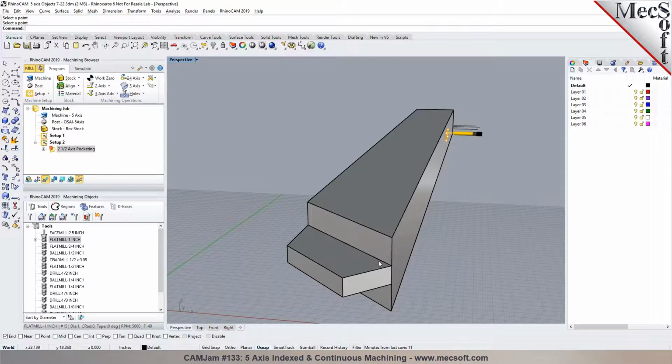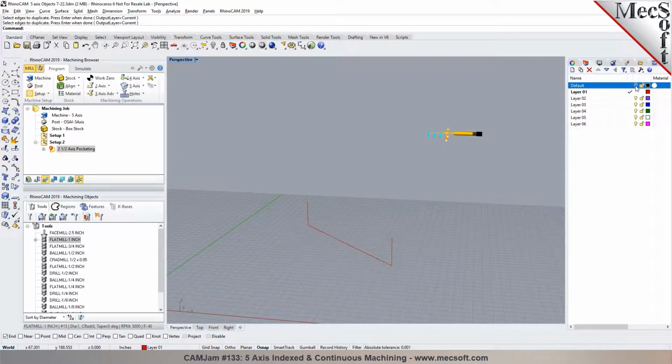The next thing we want to do is probably try to mill this with a, we don't define a saw blade cutter. The closest tool will be like a face mill. We can define it and then program this here. So what I'm going to do is prep this part here. So I'm going to duplicate edge, and maybe I'll just put it on this new layer. I'm going to extract this edge, also extract this and this edge in here. So I basically extracted some sketches from the model.